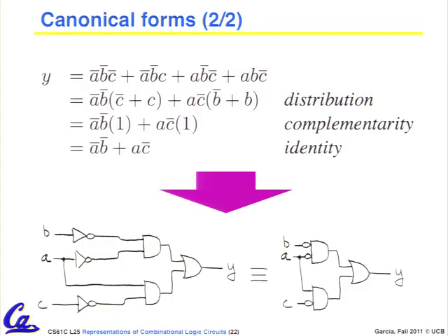So here is that example. My hands dripping with Boolean algebra expressibility. And now I can say, what can I do? Oh, look, there is not a b that's constant for those 2 terms. There's 2 different arguments, so I pulled that out. Basically, the first step usually is distribution. You pull out the common terms to get these guys. And now, here's the law of complementarity, which is going to say C or not C is a 1. If you're a human or not human, you can come in. You're definitely coming in then. And so that puts a 1. Identity then simplifies it, and there's your simplified form. Isn't that cool? Kind of cool stuff.